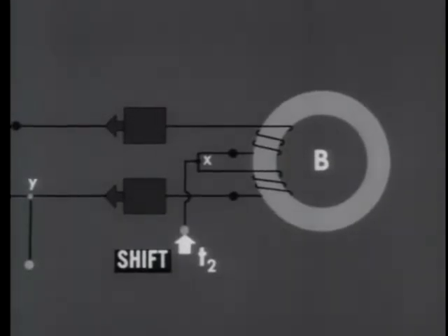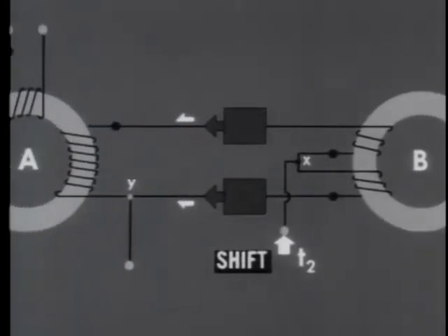As we saw before, this current goes to point X, where it divides, and the branch currents enter the two halves of the split winding. The upper branch current comes out on the non-dot side of its half of the split winding. The lower branch comes out on the dot side of its half of the winding. And both of them move along to the diodes. The diodes conduct in this direction, and the two branch currents flow toward core A.